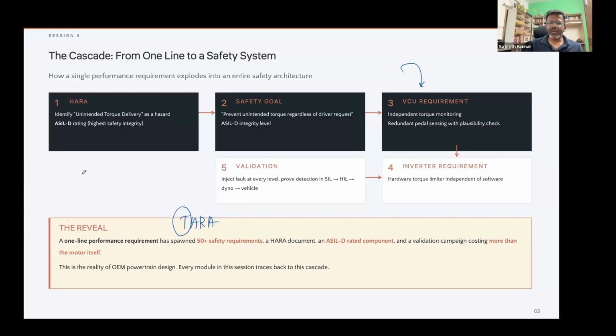Let's say they say that we need the vehicle to run trouble free for 1 lakh kilometers, right? How do you validate that it is running trouble free for 1 lakh kilometers? You should have taken your scooters and driven them on the road for 1 lakh kilometers, not just one scooter. You drive maybe 10 scooters, 20 scooters, some in Madurai, some in Leh Ladakh, some in Rajasthan, some in Kolkata, some in Chennai. You drive it in all the different locations you might sell your vehicles to.